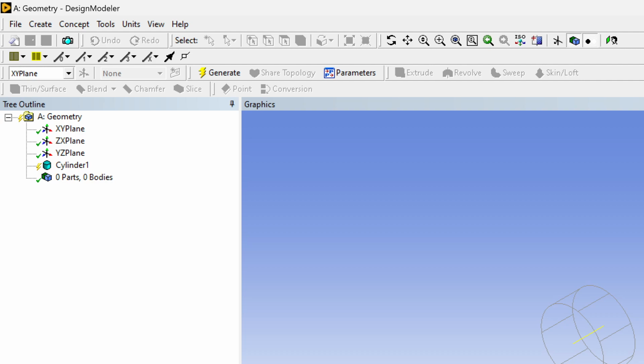The other option is asking us to essentially tell the software how to build this. We can build it based on coordinates or based on selections. We're going to keep the coordinates because we haven't really defined any points here. So the x coordinate origin is 0 meters, y coordinate origin is 0 meters, z coordinate origin is also 0 meters, and then it is going to move 0 meters in the x direction, 0 meters in the y direction, and 1 meter by default in the z direction. I'm going to change this to 10 meters because we want to have a 10-meter beam, right?